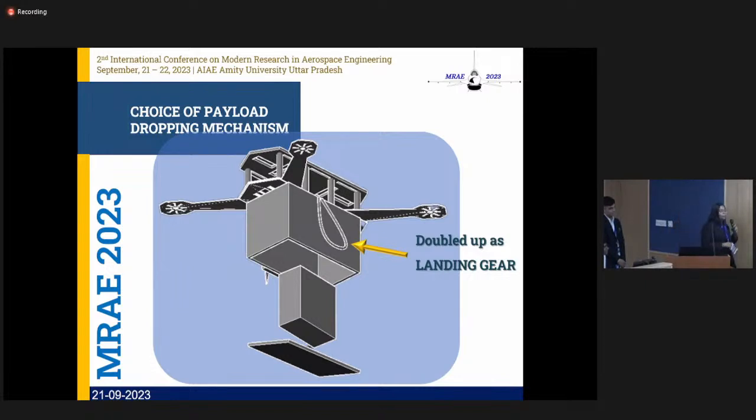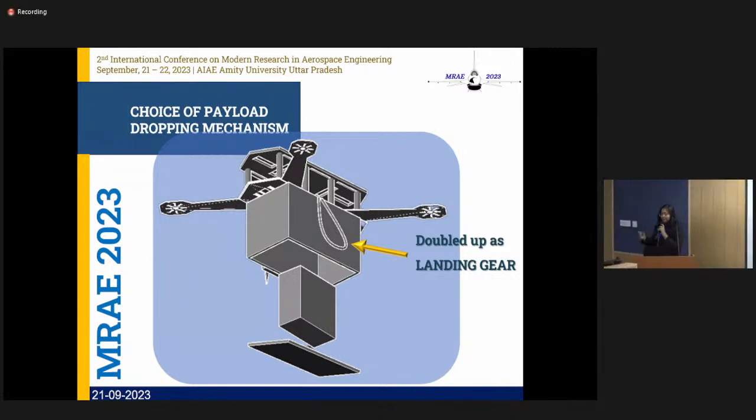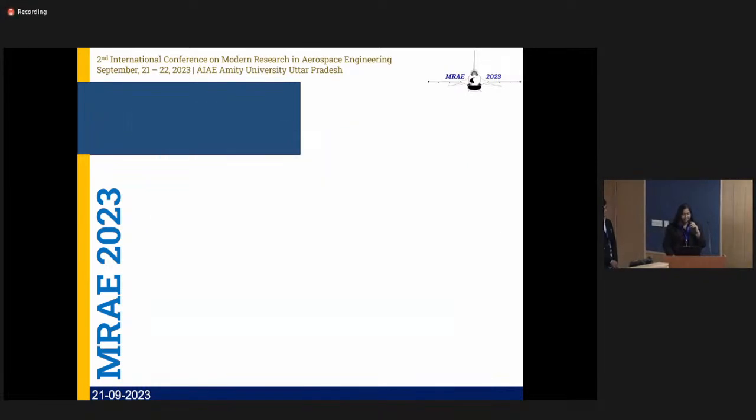Then also, one very important point: this door you see here, we could have added a hinge and made it a reusable version where we can open and close the door based on our need. But we tried that, and the problem was it made the drone unstable, especially during takeoffs and landings. So we decided to choose this design, which gets rid of the door once not needed.